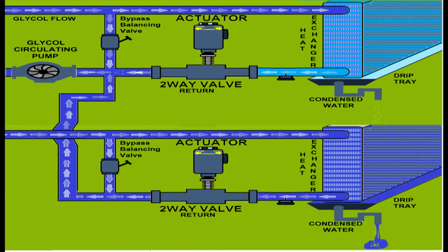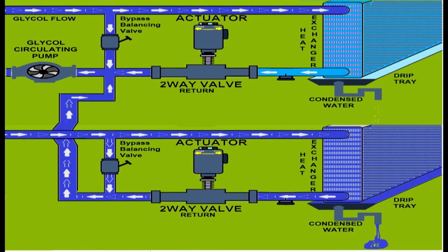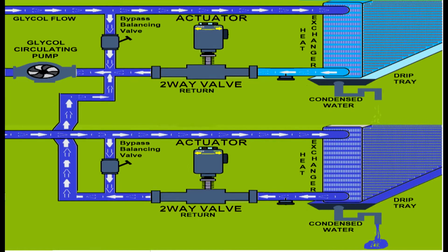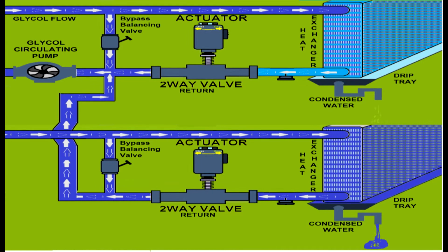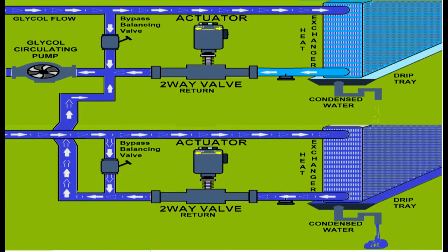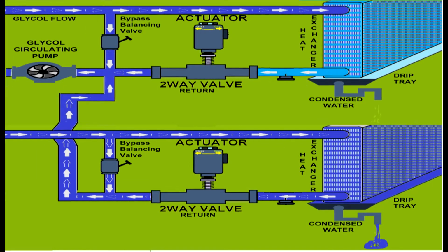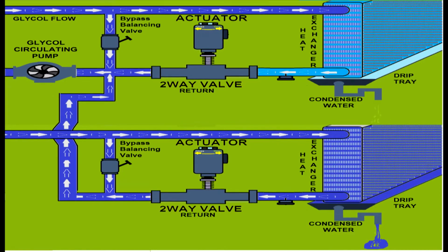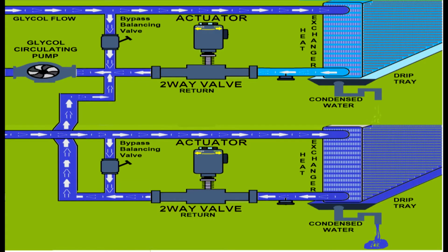I worked for Marks & Spencer, and I found small units using actuators for only one heat exchanger, and the boiler was within 2 meters. So the boiler was overheating all the time because the actuator was closing the loop. It would be easier to control the temperature by modulating the boiler than by modulating an actuator if you use this boiler to heat only one heat exchanger. Even if you use a chiller, the chiller will have its own inertia and will overshoot, because if you are closing the loop and the circuit becomes very short, the chiller's water heat exchanger can ice up.